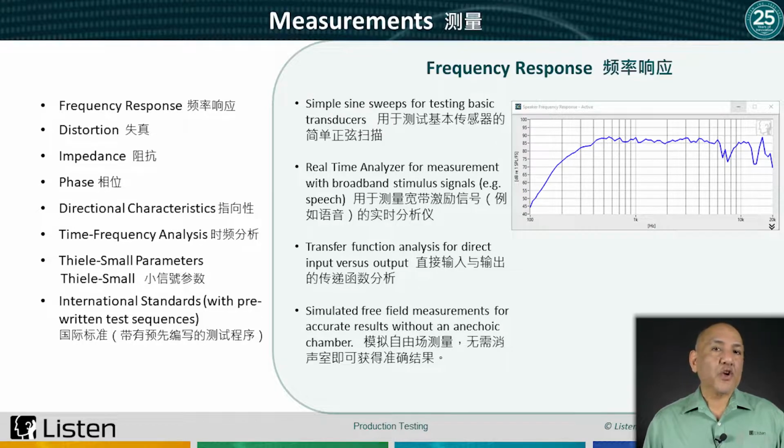In SoundCheck, there are many ways to characterize frequency response using different test stimuli like step sweeps, wideband pink noise, a reference wave file of speech or music, and even simulated free field measurements using time selective response. Frequency response is an essential measurement for production testing.